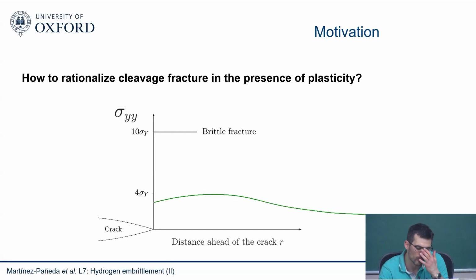So what I mean, you need to hit this stress. Not only do you need stresses that are big enough to nucleate a crack, but the stresses need to be big enough over a sufficiently long distance. At the end, energy is stress over a distance. So your stress needs to be sufficiently high over a long distance, such that eventually you get enough energy to rupture this grain boundary or whatever cleavage plane you're interested in.